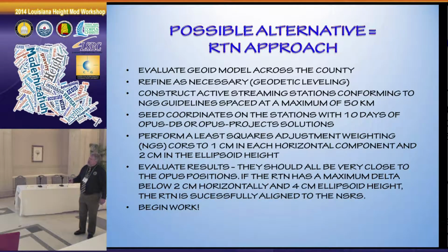But the key there is, what is truth? Is truth what's published for NAVD 88, or is it somehow related to our ellipsoid heights and a geoid separation? It should be, but how do we want to approach it?